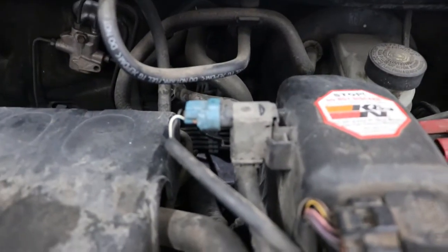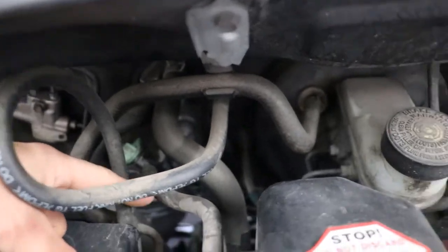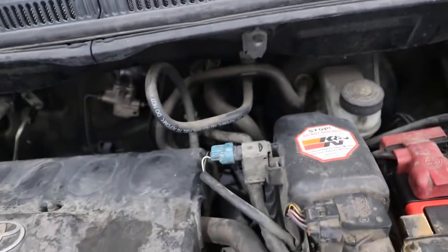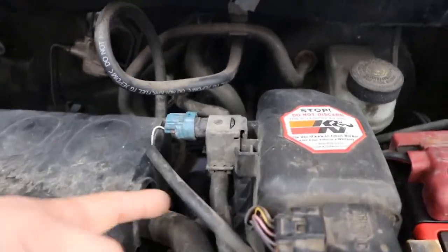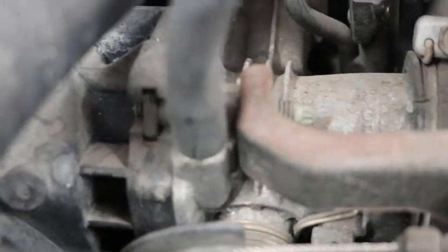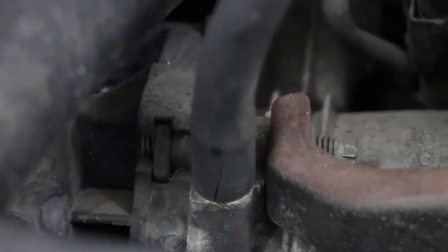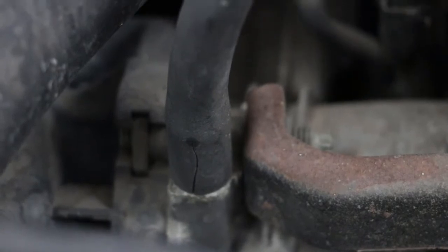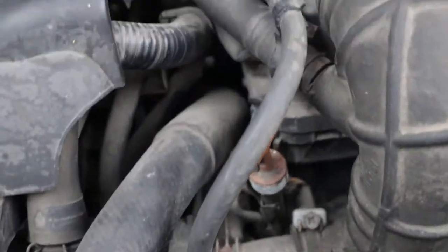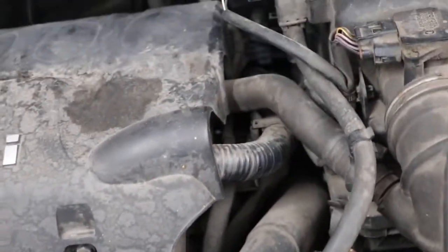So this is our vacuum solenoid valve here that comes, as you can see, the hose runs to the back here, and it's hard to see as you go back, but it does run down and goes back to the gas tank and the canister. And this is going to be the line that comes into the manifold and draws vacuum. And I'm already looking, and as you can see right here, I don't know if you guys can see that, and as we follow it down, you can see there at the intake, there is a big crack in that hose. And that hose definitely could be reason why we don't have a good seal on the system. And that comes from the manifold, comes up to the top, back to the valve here, and then again from the valve back. So already after just a small visual inspection, there is a big crack on the hose there. And that could be one of the main reasons why we're having a small leak detected.